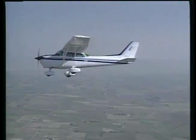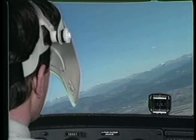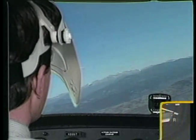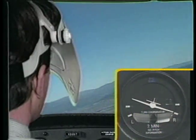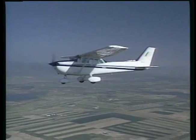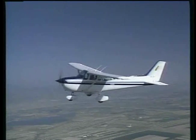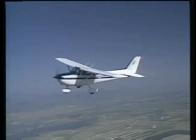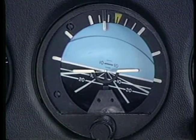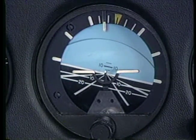The next maneuver we'll look at is performing a turn. All turns by instrument reference are made at a standard rate of 3 degrees per second. When the miniature airplane in the turn coordinator is aligned with the reference mark, you are in a standard rate turn. To enter a turn, establish a bank by referring to the attitude indicator. As you become familiar with your airplane, you'll learn the angle of bank that produces the standard rate turn at a given true airspeed. As the turn is established, you'll need to raise the nose slightly to offset the loss of vertical lift during the bank.